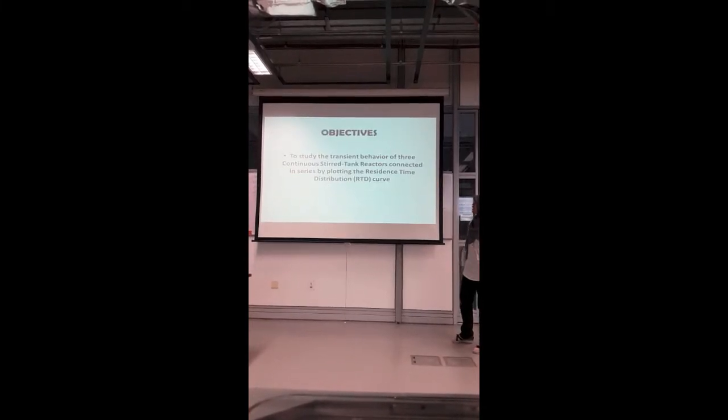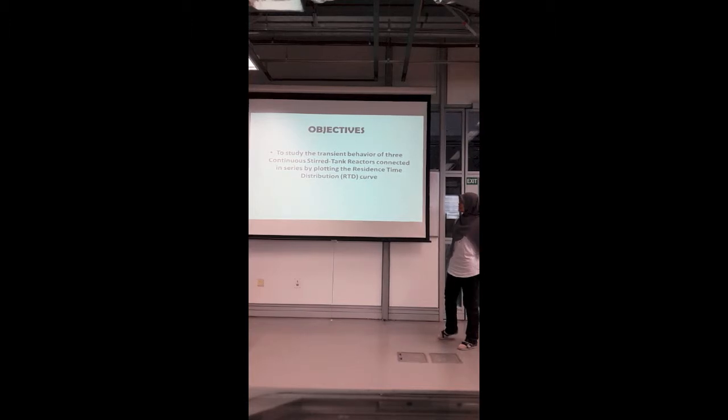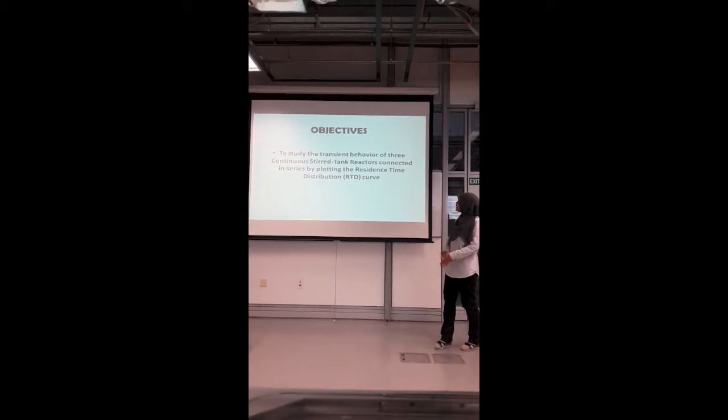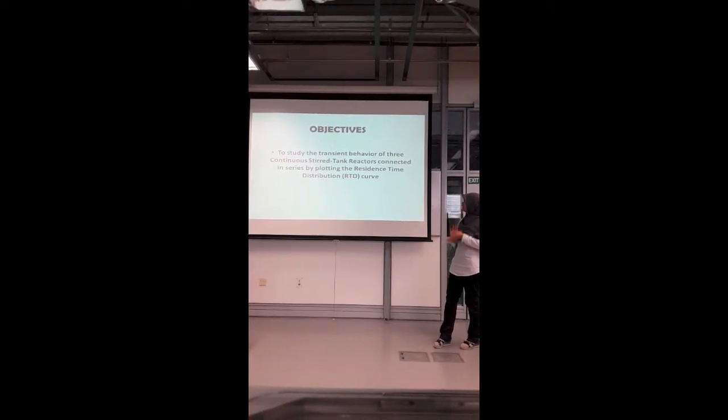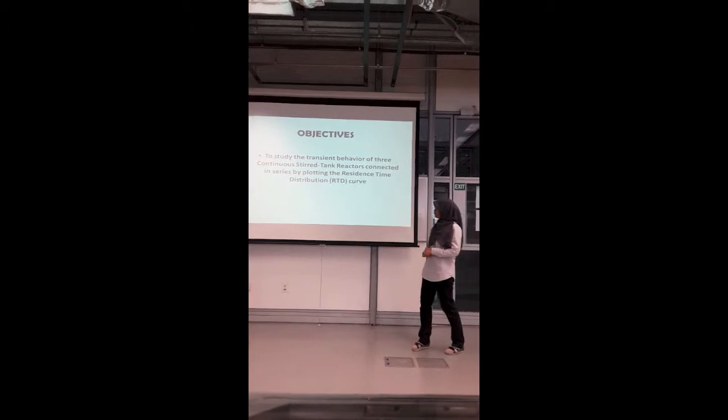Next, the objective of our experiment is to study the transient behavior of three continuous reactors connected in series by plotting the residence time distribution curve.